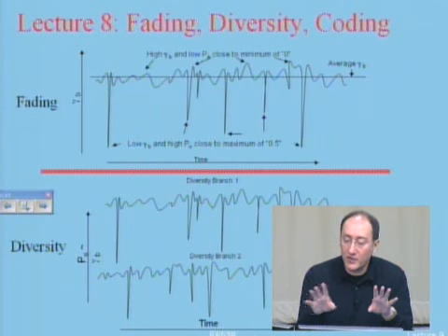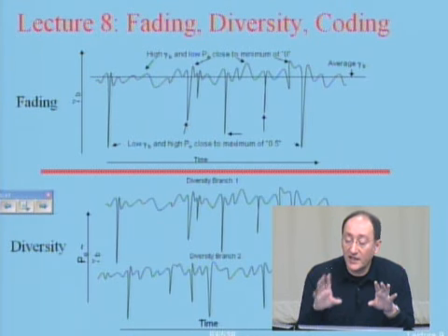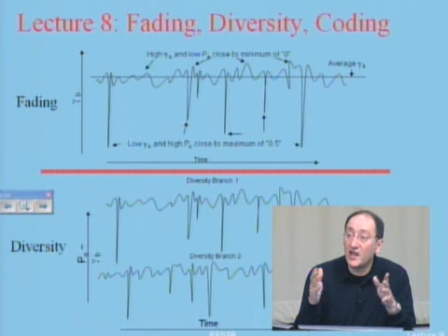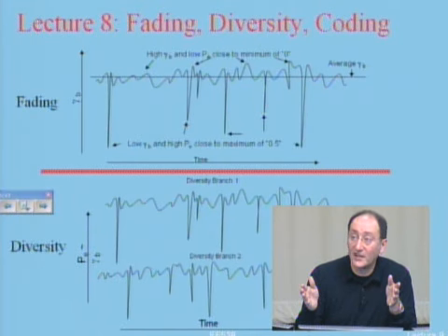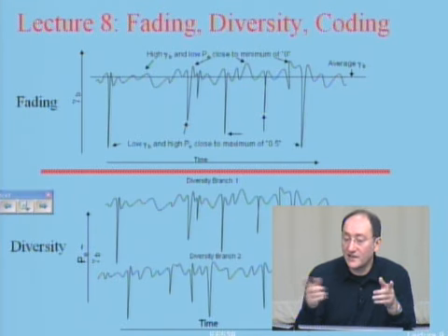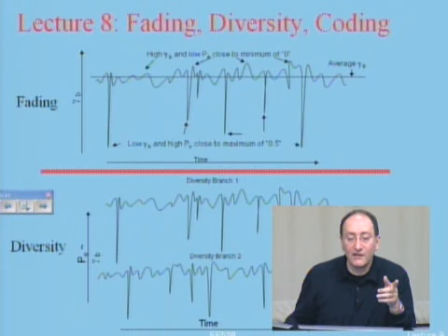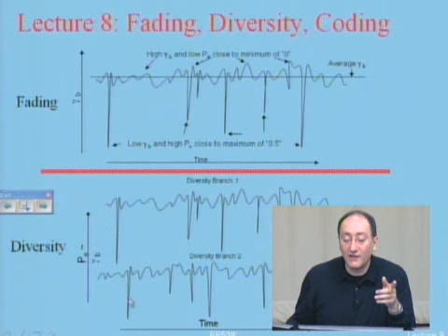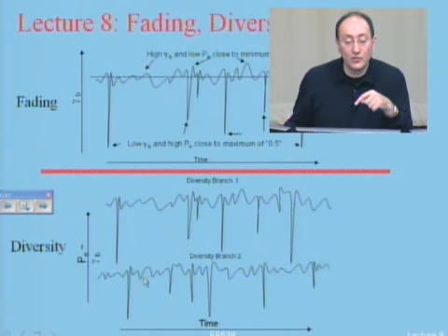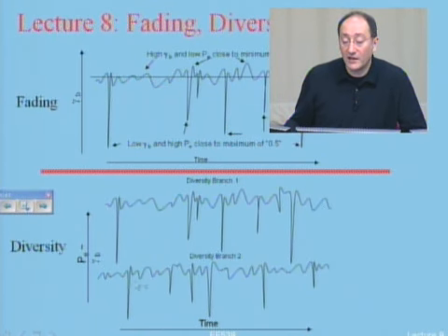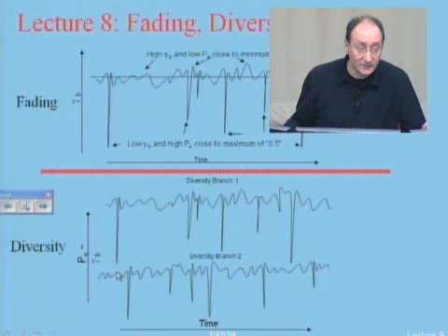So if I have independent, like Rayleigh fading channels, I can put the antennas even lambda over 4 apart. And then the phases change. Then when phases change, if in one location I have fade in here, I will have fade in the other one at a later time. So I have 2 sources of independent fading. And then I look at both of them, and whenever one of them is in fade, I use the other one, for example. That was the summary of what we had in here.